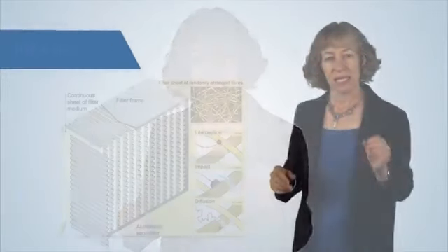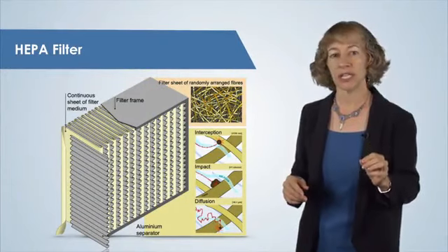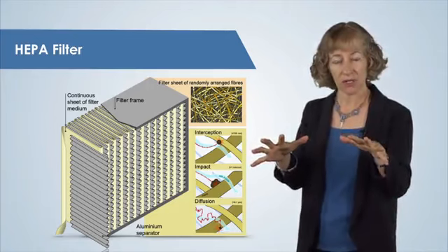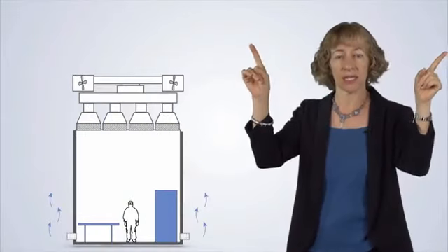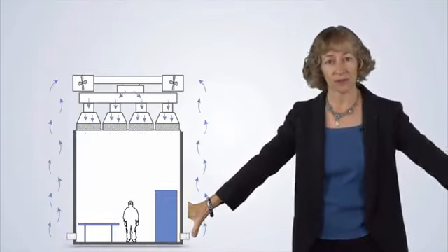Particulate contamination is controlled with special airflow in the clean room designed to filter out airborne particles and to minimize the amount of particles that are stirred up from surfaces. The key air filtration component for clean rooms is the high-efficiency particulate air, or HEPA filter, that is used to trap and filter out particles that are 0.3 microns and larger in size. All of the air delivered through a clean room passes through these HEPA filters, which are typically located in the ceiling. The extra air is then typically flowing out through vents near the floor.